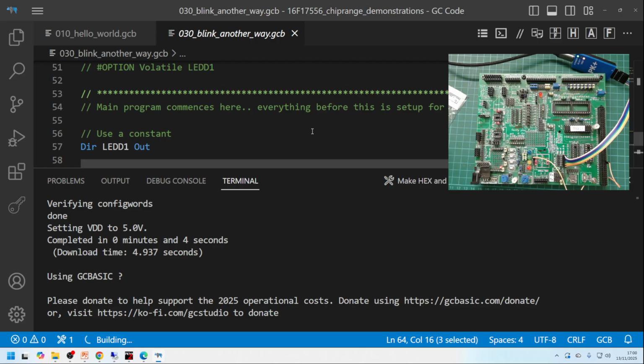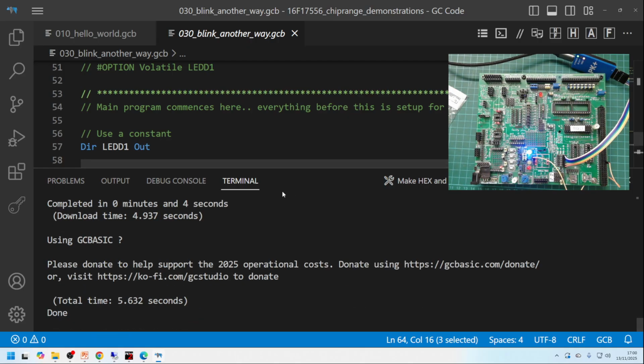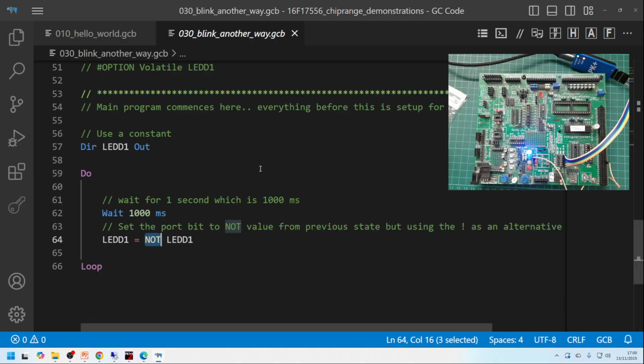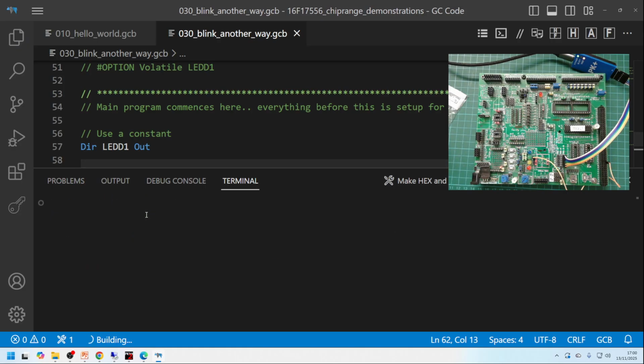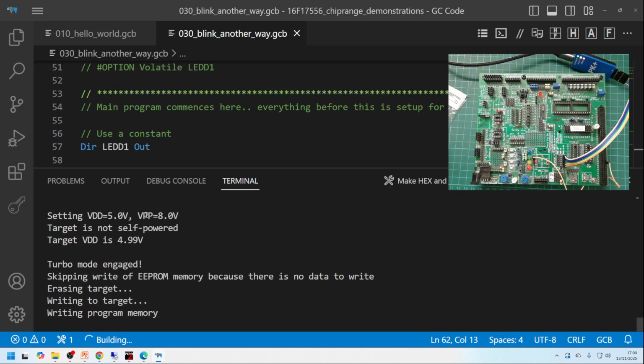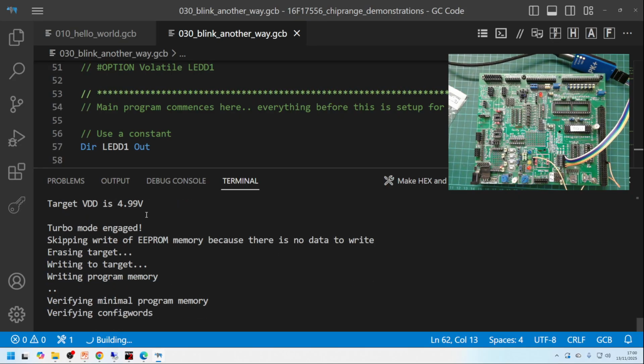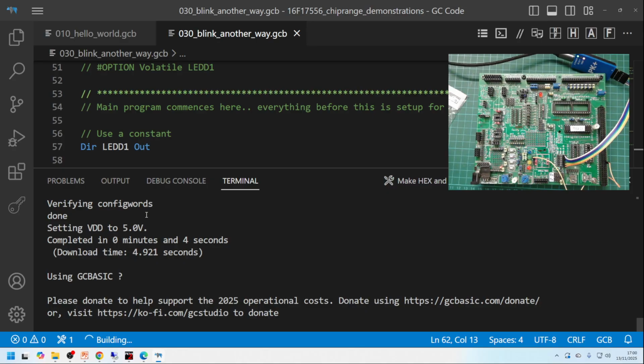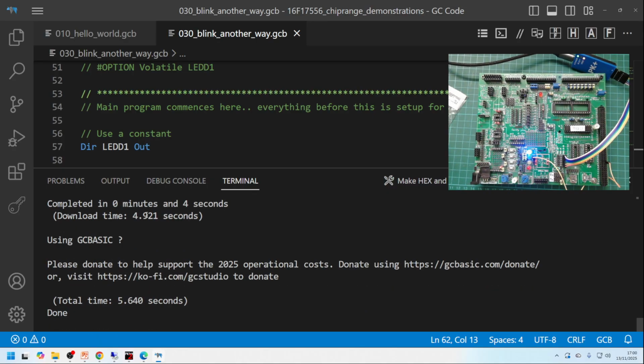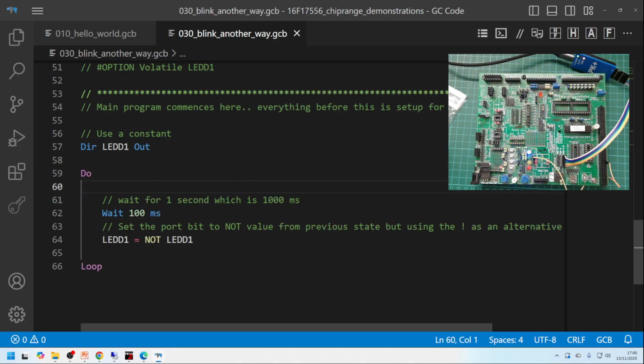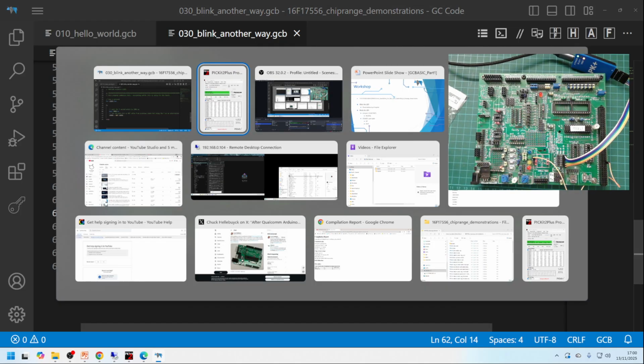And you might say, it hasn't done it. Well, what we can do, of course, is change the value here. We'll just knock the 0 off the end there. Reprogram it. And you can already see that the program at the top there is flashing its LEDs, and now it's flashing faster, every 500 milliseconds. We could put an oscilloscope on that, but trust me, it's doing its stuff. I'll revert that and save it. Standard save, Alt F S. Very, very simple.